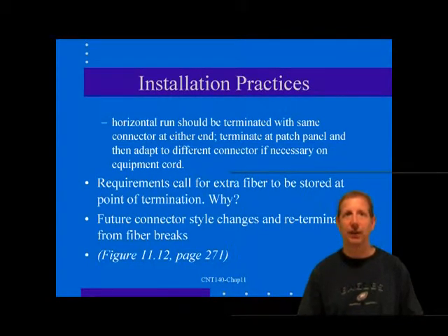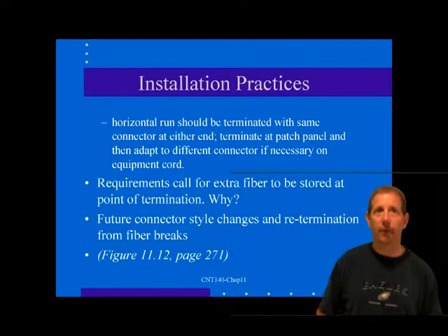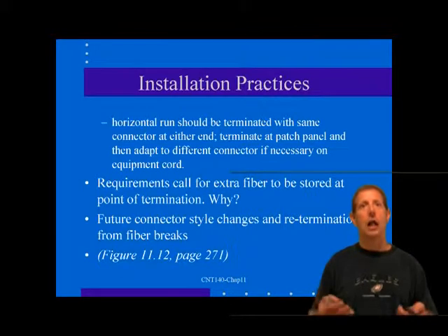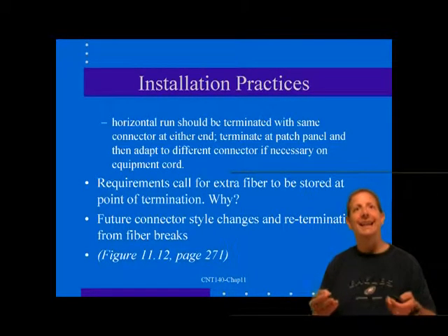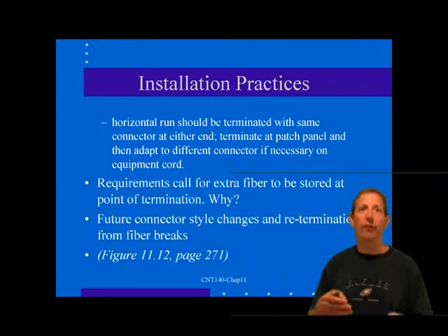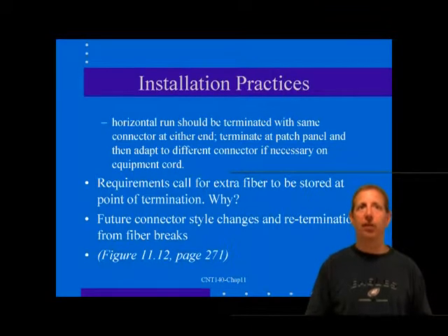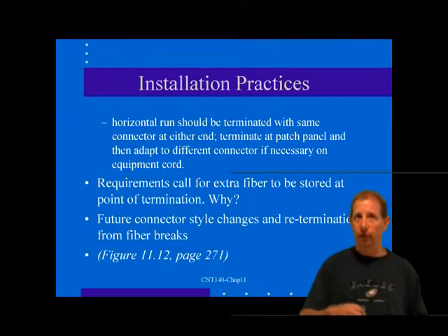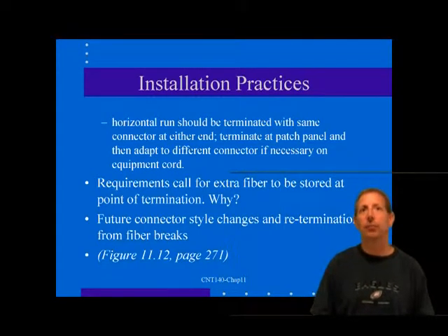For example, an SC equipment connector could easily be interconnected to an SFF connector patch panel with an appropriate adapter cord. Likewise, the same type of transition could be made at the end user cord. The SFF connector types offer so many varieties that an abundance of adapter cables will be made available. In addition to adaptation to the legacy connectors, which would include the 568SC, cords must be available to transition between each of the popular SFF types.